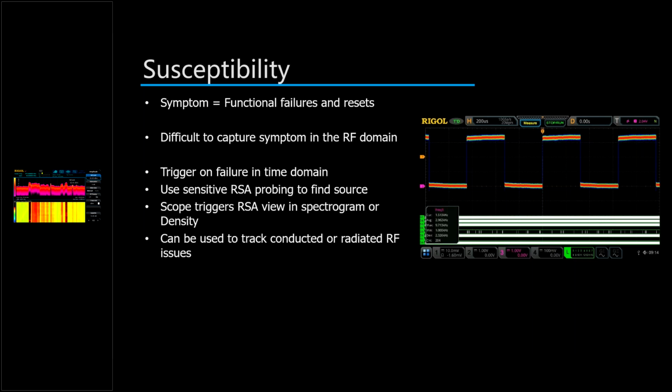We can easily trigger on these sort of pulses and these resets by doing a couple different recordings on the scope side. So we can analyze what's happening. But we've looked through our embedded system. We've looked through all our digital channels. We don't really see what's driving this problem. We've talked to the software guys, and the FPGA code doesn't seem to be causing this kind of problem. So we have to look further.